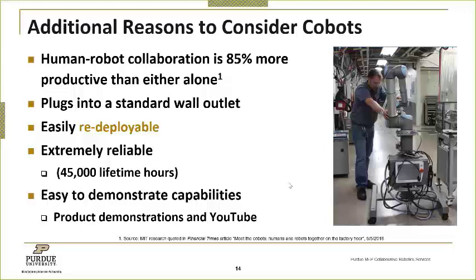Whereas people are better at problem solving, right? And going around obstacles. So where a robot might get stuck if there's a jam in the part feeder that's feeding it the blanks to put in a CNC machine, a person can walk up to that thing, bang on the side of the feeder, or clear the feeder and get it going again. So that's really where that synergy between humans and robots working together can bring benefits on the factory floor.